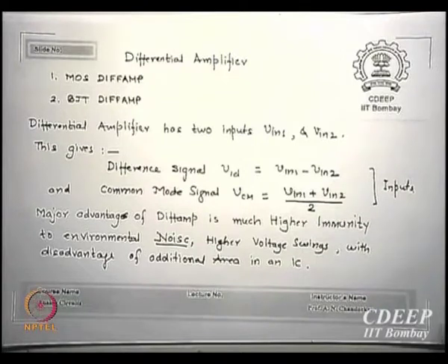Okay. Now first thing first, why are we so keen about diff amp? Till now, with all the amplifiers we have seen, we can have a gain of any stage by cascading or by cascoding. By cascode I can also fool people by not losing bandwidth but getting the gain higher. So why am I interested in differential amplifier? Here is a big advantage which a differential amplifier gives over all single ended amplifiers.